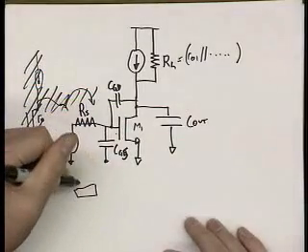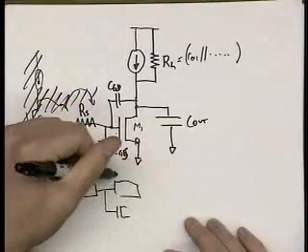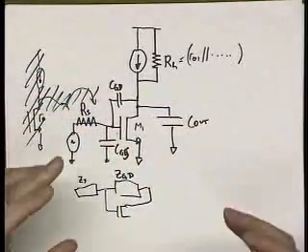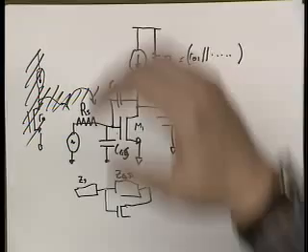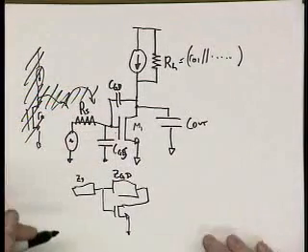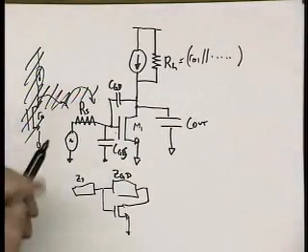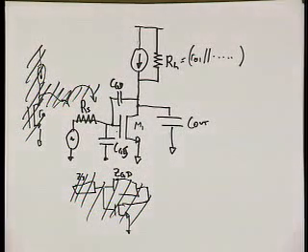So I'd call this ZS, and I'd call this ZGD, just because ZGD is more compact than 1 over j omega CGD, and do all the mathematics and then plug in what your actual impedances for each of those branches are. I like that technique. You don't need to use it, but I think that if you were to do it, you'd be happy doing those substitutions. Anyhow, that's still too tedious, so we want to start using some intuition.